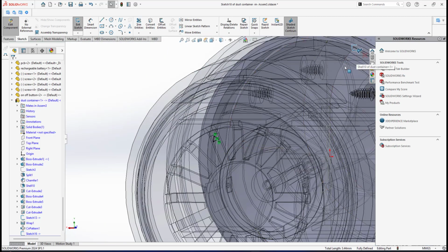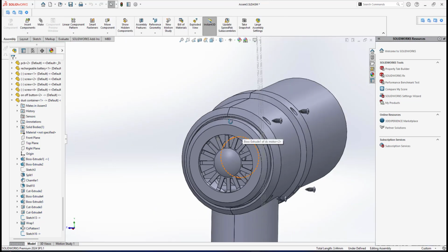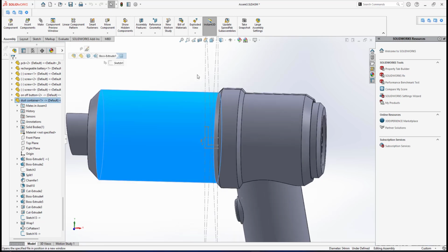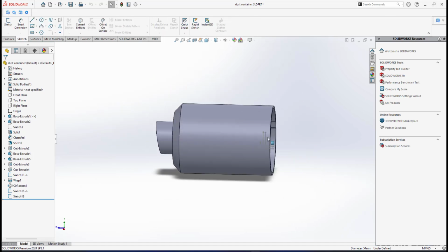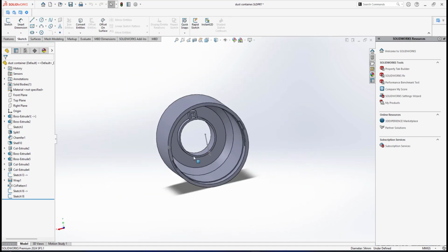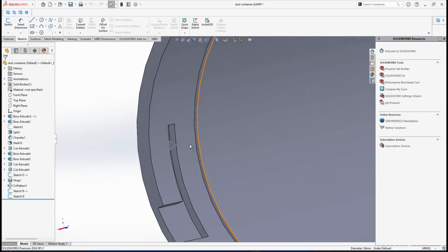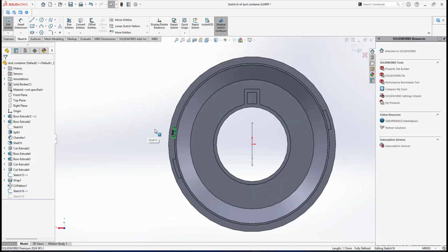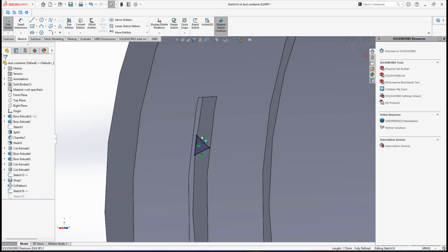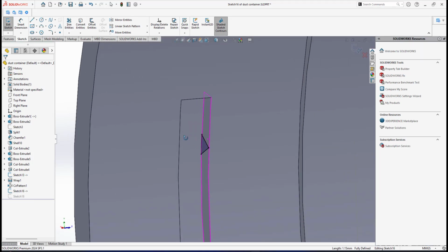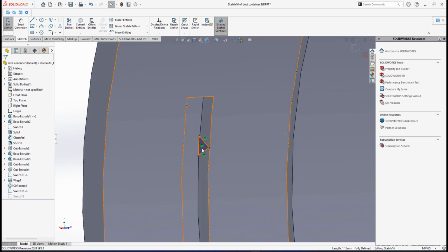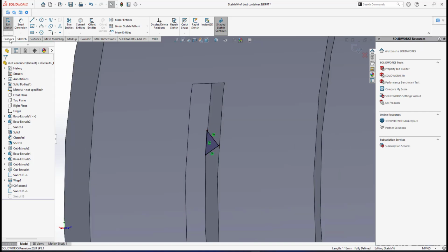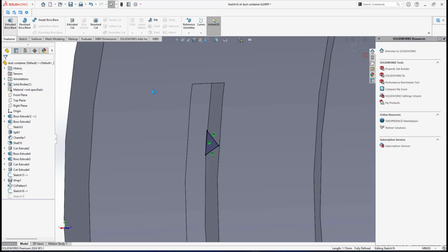Okay, I exit the sketch and also exit the edit part mode. Now I can go back to part modeling mode of this container. As you can see, I now have the trace outline. This one I can edit the sketch, and since the L key of the main body file is a V groove, this one will be the invert of it, so this will be the V key. So I will do features, boss extrude.